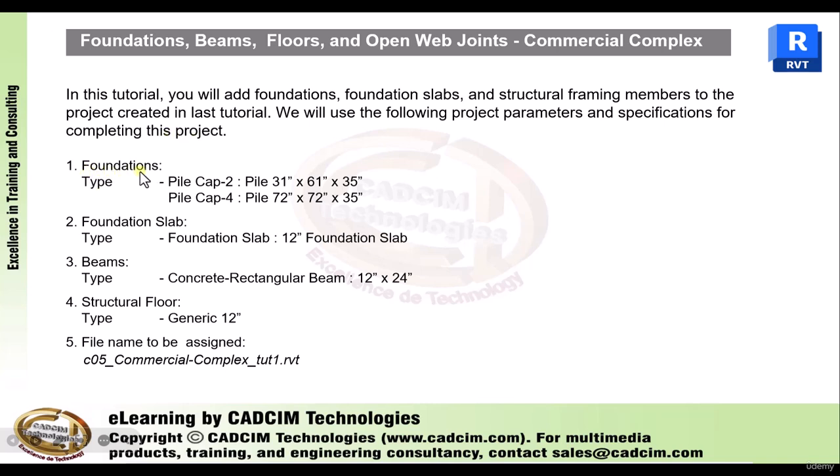The first project parameter is foundations: Pile Cap 2, 31 inches by 61 inches by 35 inches, and Pile Cap 4 with 72 inches by 72 inches by 35 inches types. Second one is foundation slab with 12 inches foundation slab type. Third one is beams with concrete rectangular beam of 12 inches by 24 inches type. Fourth one is structural floor with generic 12 inches type, and fifth one is file name to be assigned as C05 Commercial Complex Tute 1.